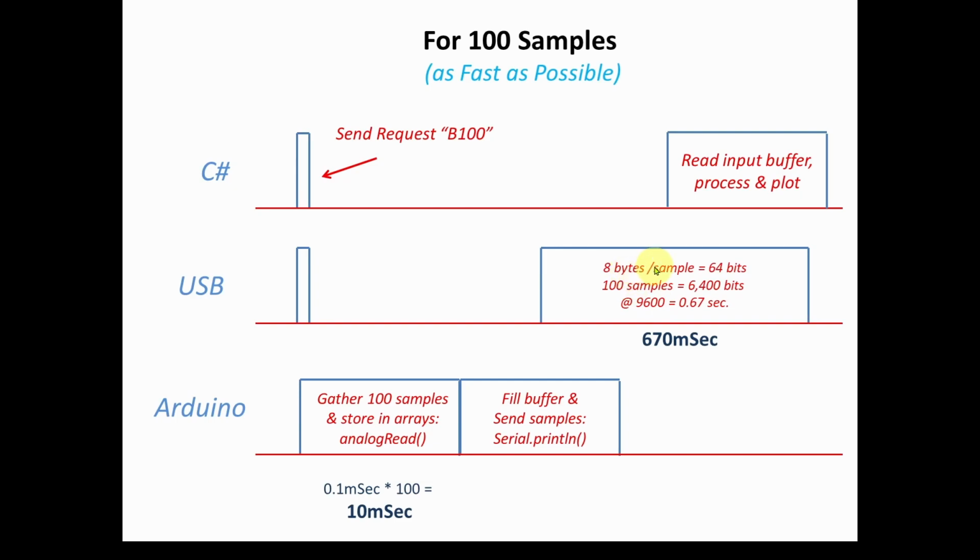So let's just say each sample is a time and a value, and let's say there's a total of 8 bytes being sent in each sample. Might be more, might be less, but at least this is a ballpark depending on the size of the numbers we send. So 8 bytes per sample and 8 bits for every byte. That means 8 times 8 is 64 bits we're going to send in each sample, all right? Again, just a ballpark, but at least it gives us an idea.